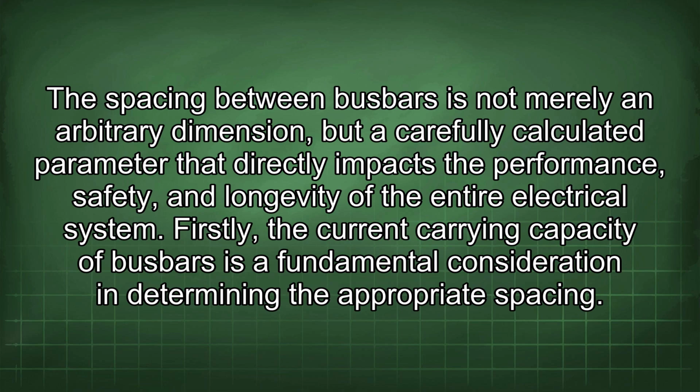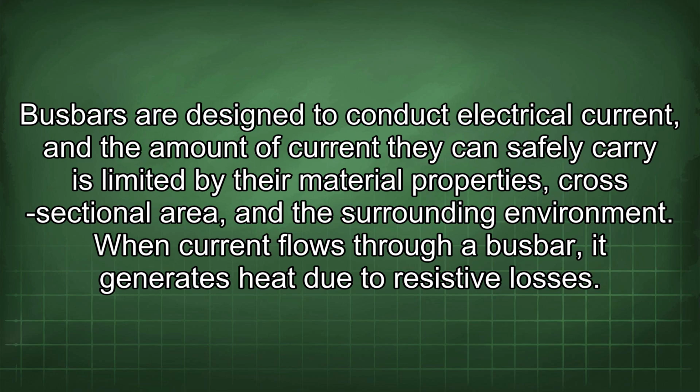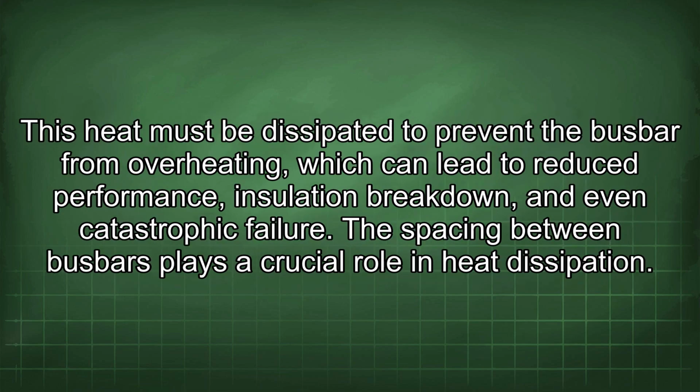Firstly, the current carrying capacity of busbars is a fundamental consideration in determining the appropriate spacing. Busbars are designed to conduct electrical current, and the amount of current they can safely carry is limited by their material properties, cross-sectional area, and the surrounding environment. When current flows through a busbar, it generates heat due to resistive losses. This heat must be dissipated to prevent the busbar from overheating, which can lead to reduced performance, insulation breakdown, and even catastrophic failure. The spacing between busbars plays a crucial role in heat dissipation.